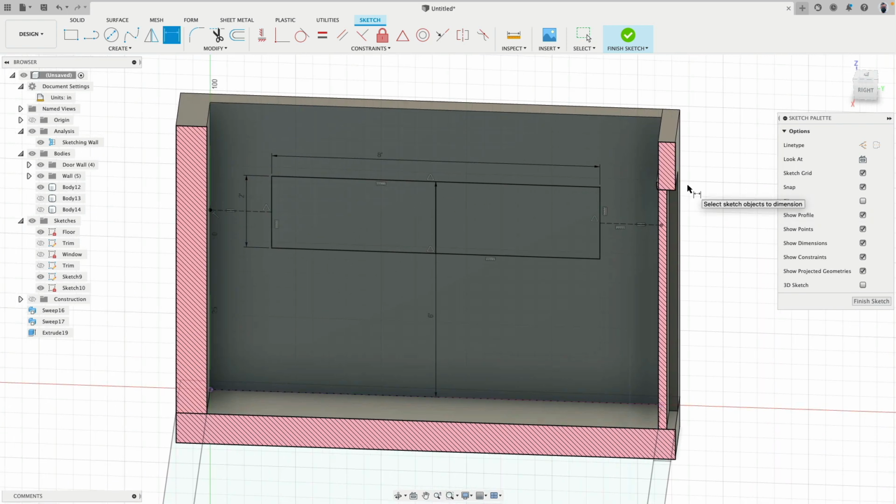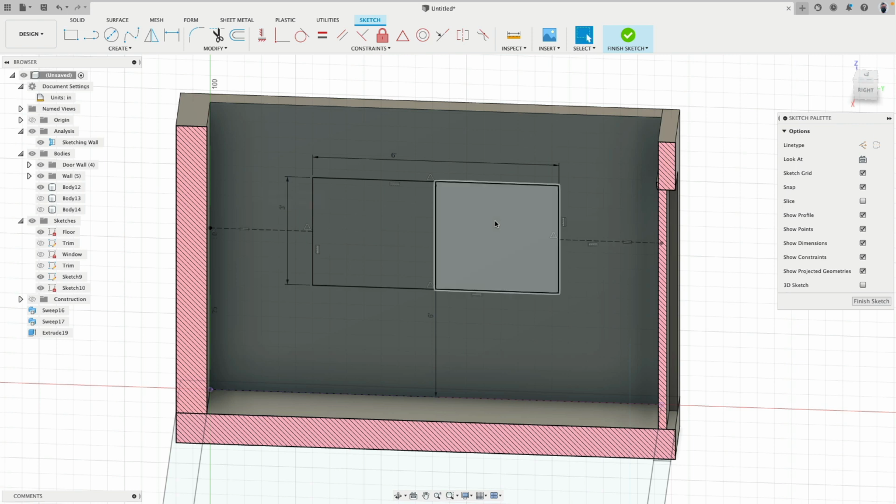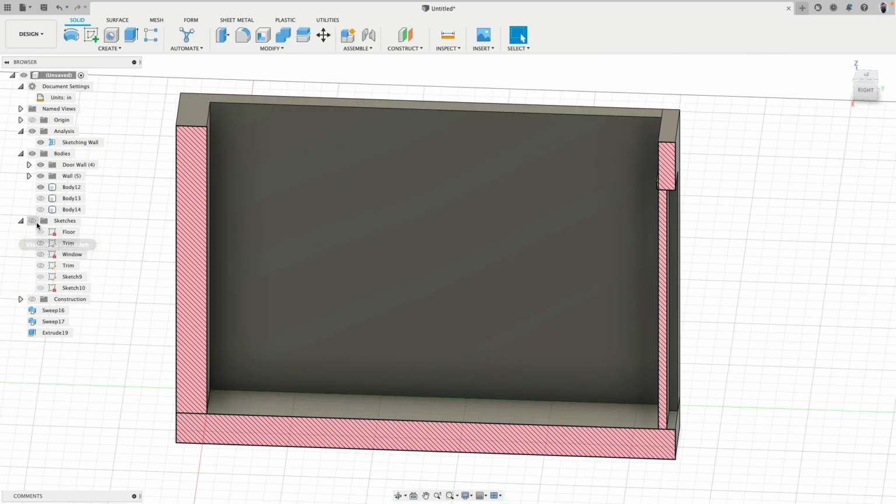Again, for those who are from SketchUp, you notice we don't really have to work with guidelines because how we start dimensioning everything, that's actually interactive guidelines. Because the nice thing is I can go ahead and say, well, what about I make this 6, whoops, not 6 inches, 6 feet. What about we shrink this down or grow this down by 3 feet? You see how the sketch very nicely adjusts. Very good. Finish sketch. There we are.